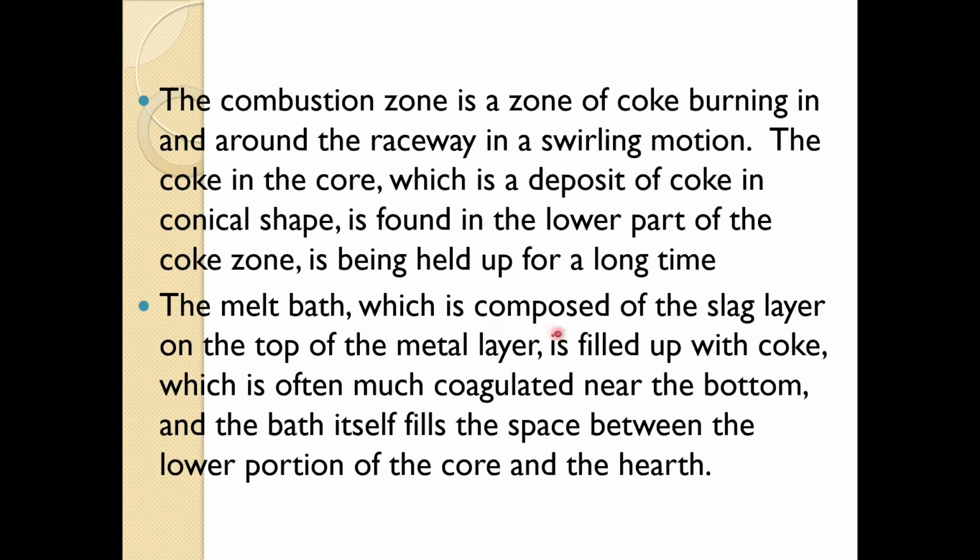The melt bath, which is composed of a slag layer on top of the metal layer, is filled up with coke, which is often much coagulated near the bottom, and the bath itself fills the space between the lower portion of the core and the hearth. So, essentially all the slag and iron is sitting in between the holes of the dead man.